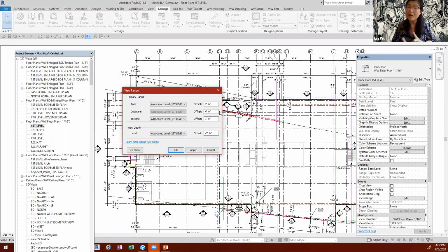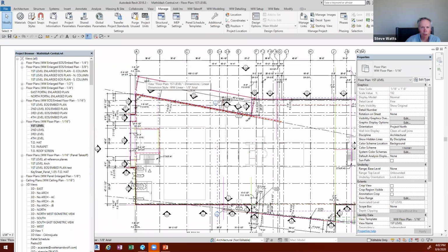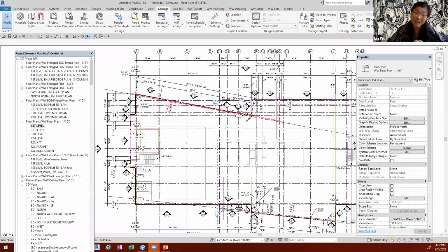But I know they have a way to do it in Revit. You just need to set it up right. We can change the location of the cut plane if you want. It's really relying on the job drafter, because every job is different. Your cutting plane can be maybe 15 feet high or 10 feet high or 0 feet high.